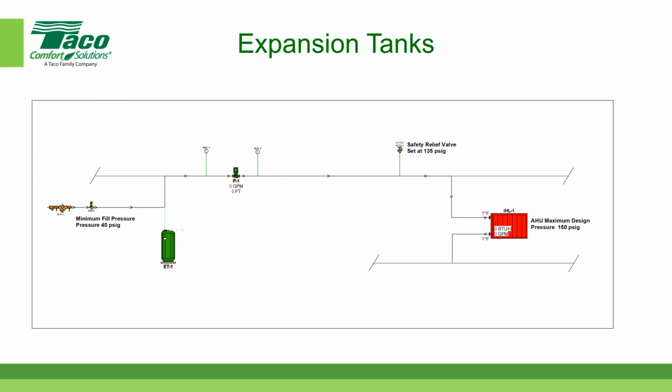Now, relief valves are very simple devices. They basically have a disc. That disc is held closed through a spring, so they're not all that accurate. So if you get close to the setting of the relief valve, in terms of pressure, as I approached 135 pounds in the piping system, let's say I get to 134.5, then that valve could potentially start to leak or weep, drip water out of it.